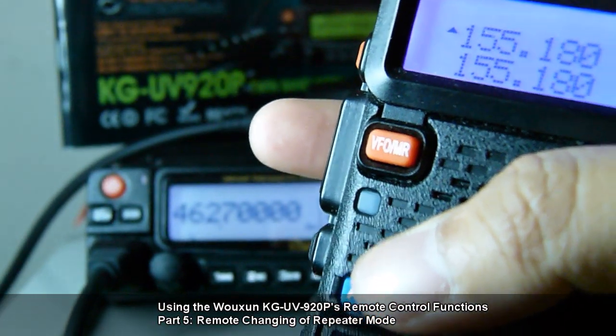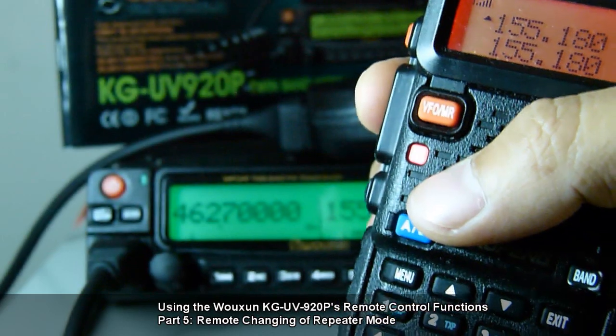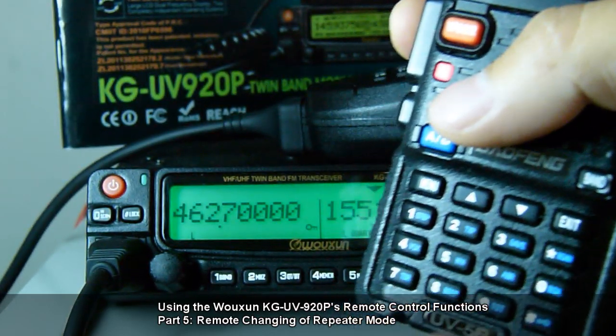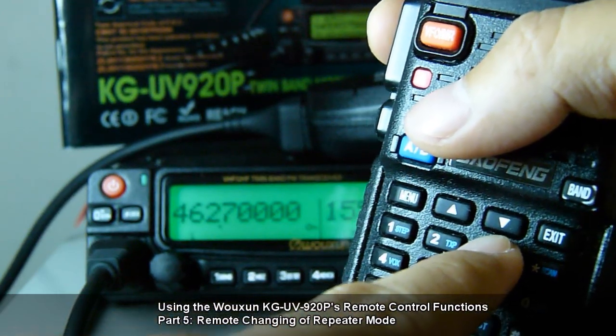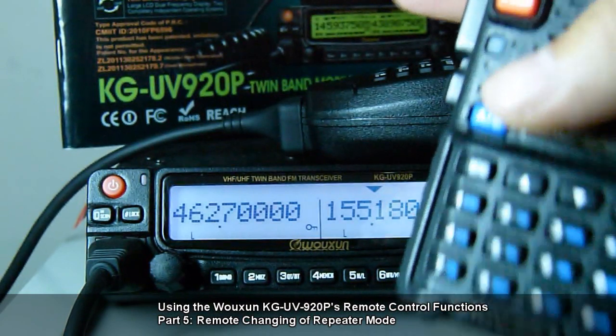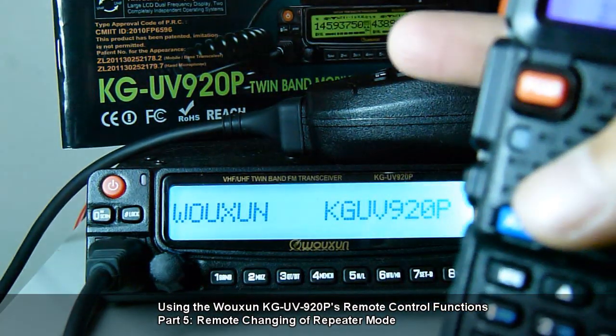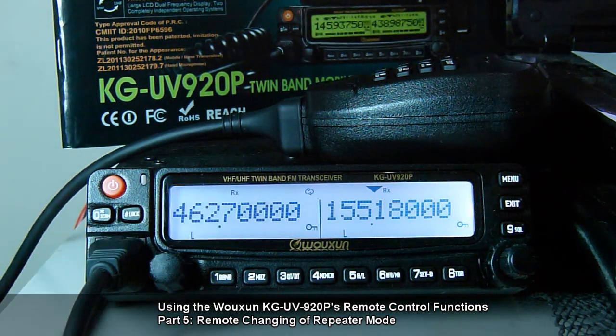Okay, you heard the beep there, and then within 30 seconds you hold PTT again, as you can see there, you do 0, 3, and then 3, and release the PTT. Okay, after the beep, the KG-UV920P would reboot, this time to two-way crossband repeater mode.